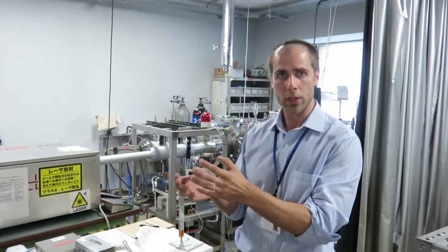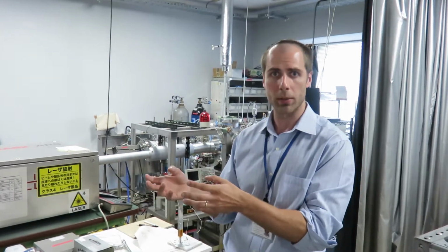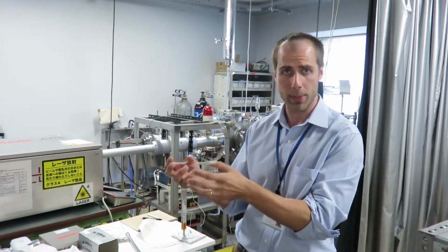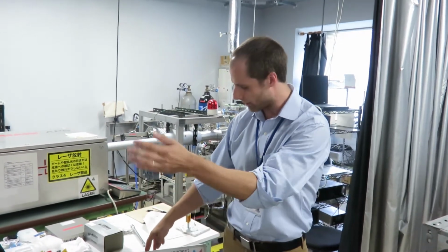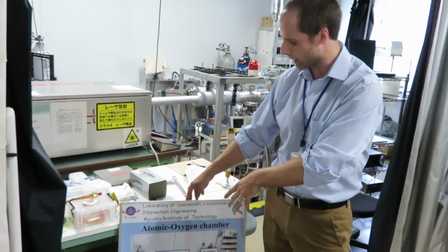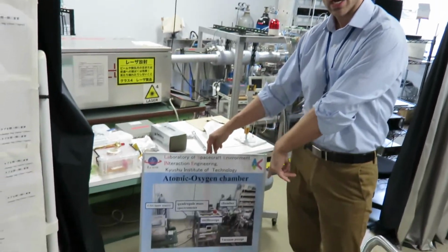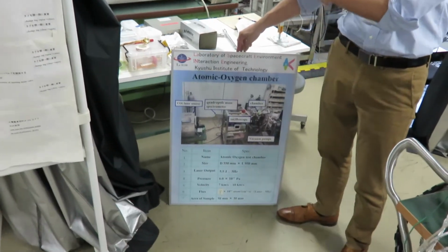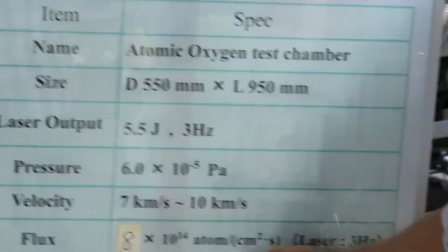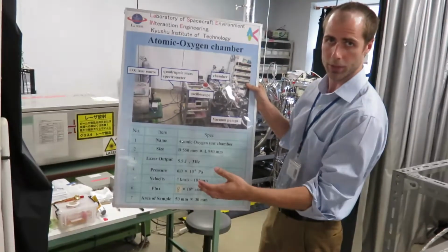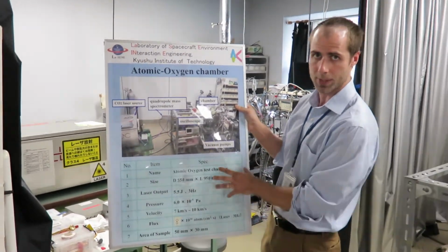Around Earth's surface, oxygen, nitrogen, and a few other molecules are diatomic, found in pairs in nature, but in the exosphere, above the four main layers of the atmosphere, we have atomic oxygen. This oxygen is photoionized by solar energy, UV energy from the sun, and this atomic oxygen is very chemically reactive, and can cause harm and degradation to satellite materials and other objects in space.